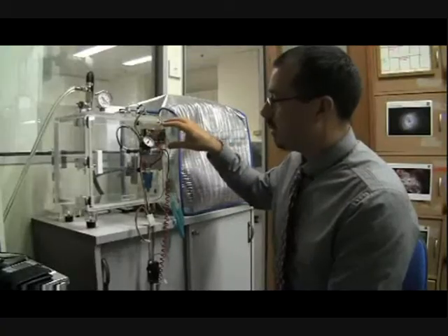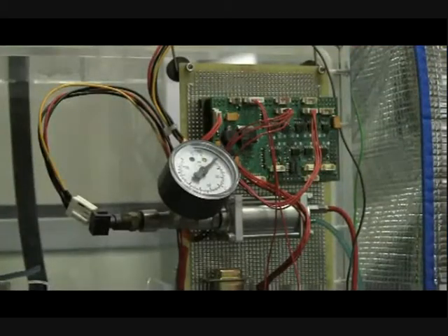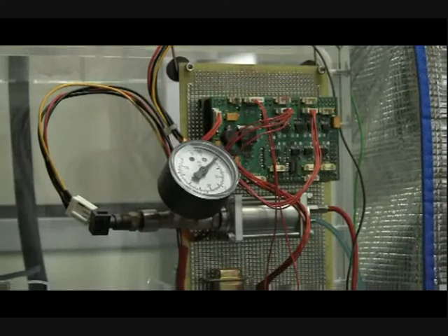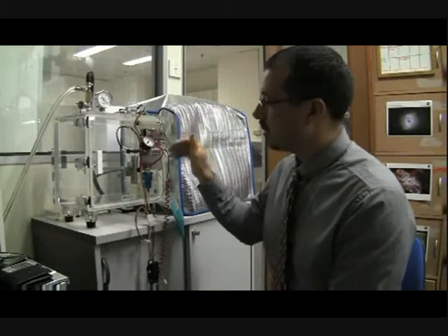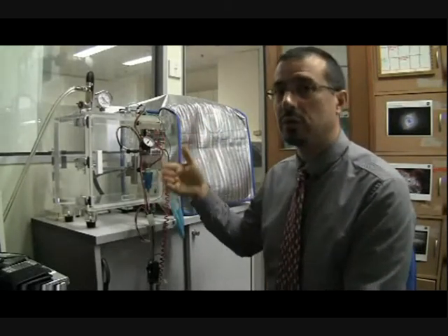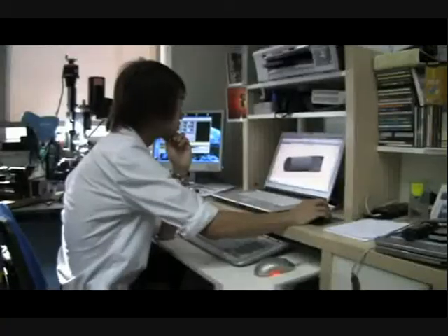Then we have outside the machine the same electronics that go into the satellite, so it's the same electronics that control the nozzle itself, and a small tank that contains a certain amount of gas, that is the propellant. And by measuring the pressure in the tank, we know how much propellant has been used for each pulse of thrust, and so we can calculate the efficiency.